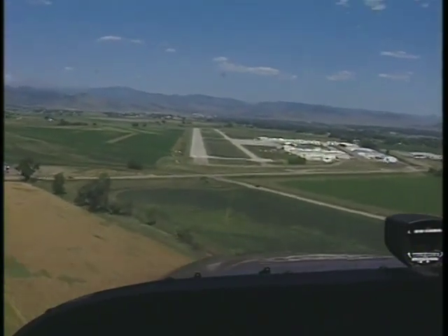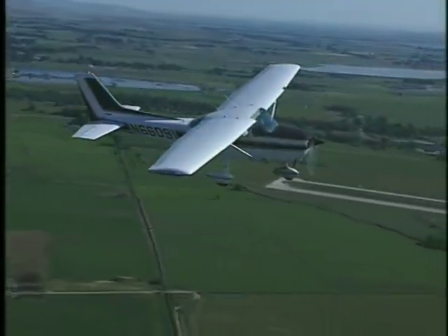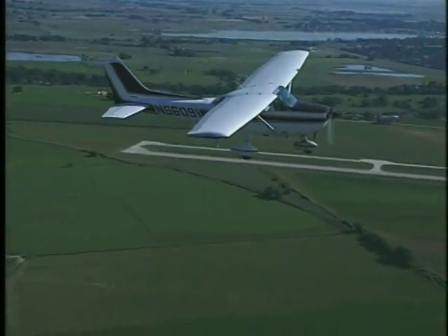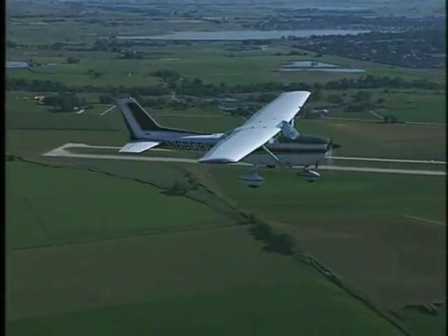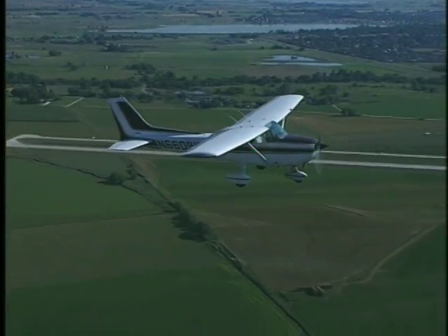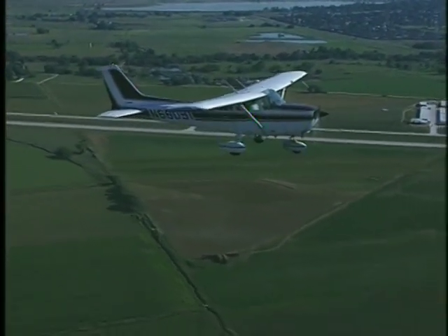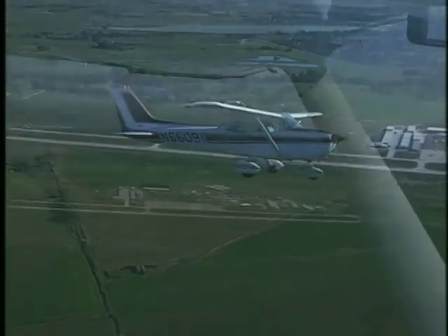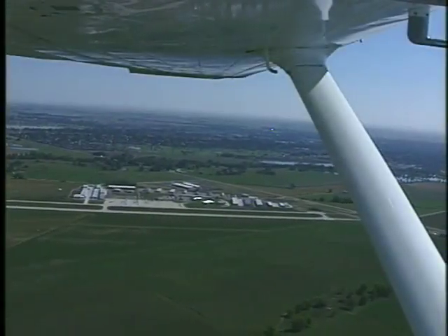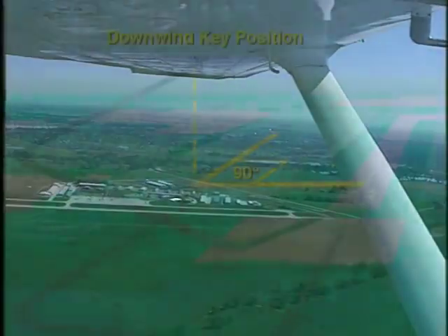the effects of wind. The approach begins on the downwind leg with the aircraft at pattern altitude, typically no higher than 1,000 feet AGL. Make your normal pre-landing checks, including the extension of the landing gear if necessary. While on downwind, select your point of intended landing.